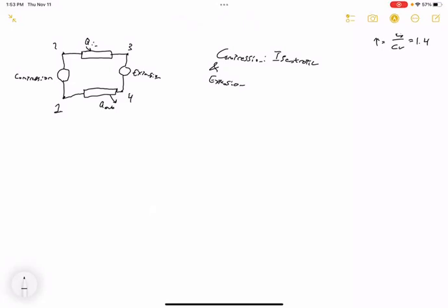Now, what does an isentropic process mean physically? Well, from the name isen-something, we can tell that it's the same, whatever we're talking about, entropic. So the entropy of the system has to be the same. So if we say that the compression and the expansion are isentropic processes, that means that going from 1 to 2, the entropy is the same, and that going from 3 to 4, the entropy is the same.